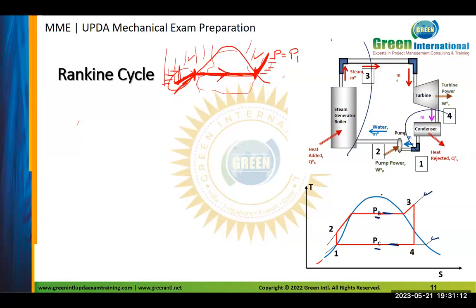Great, that's fine. We started by point 1 here, into the pump. So this is the point into the pump. At least saturated liquid. It's better to be subcooled to be sure this is fully liquid. This is the pump, so we need to be sure this is pure water. So from this going up, isentropic process. So the pump process is isentropic. Also the turbine. Pump and turbine are isentropic processes. Normally the parts for the work calculation are isentropic.